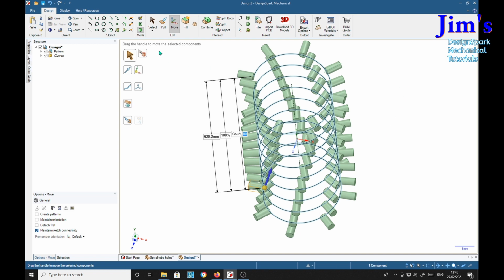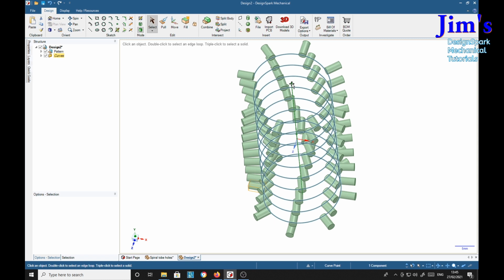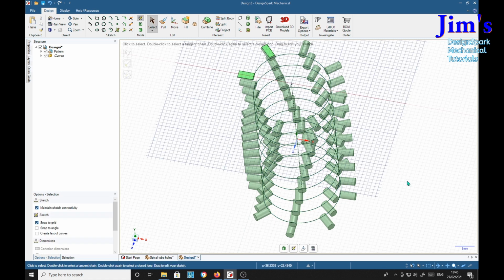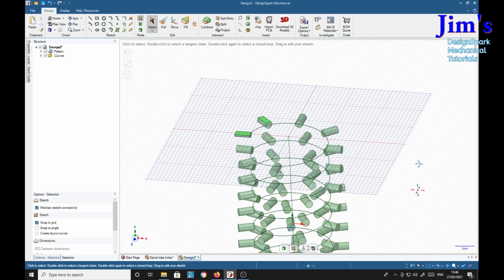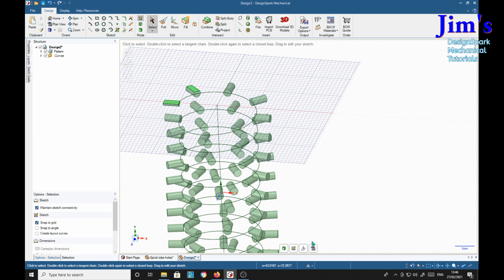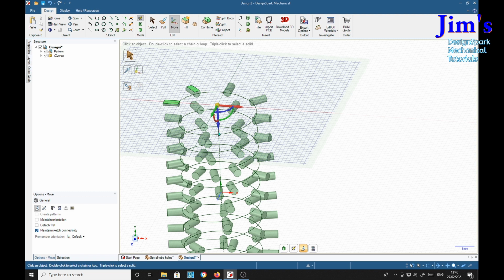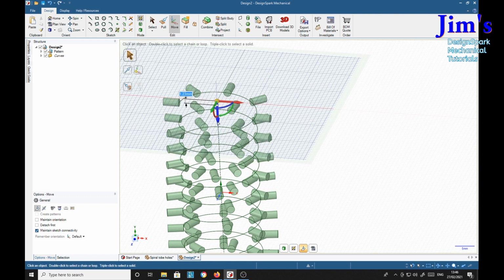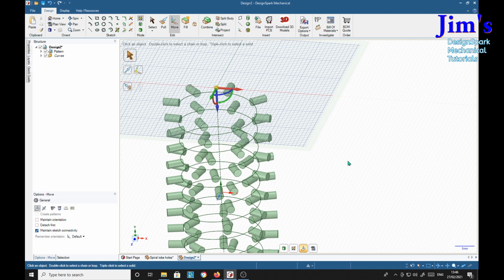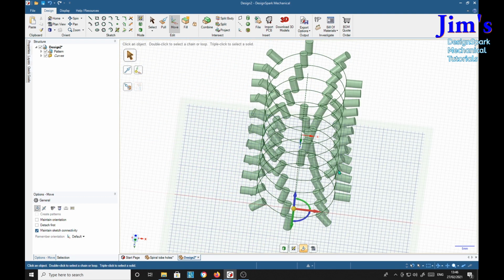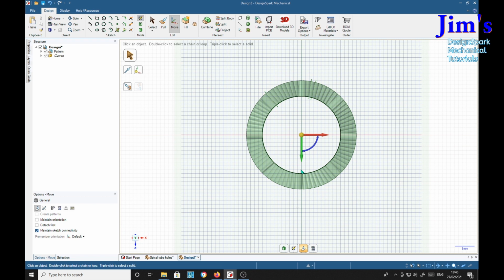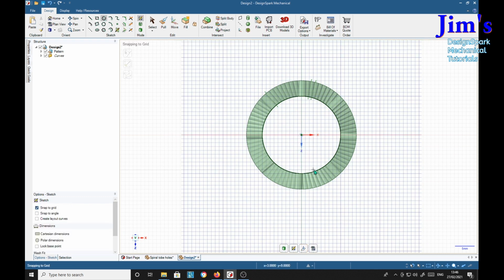So now we select again the end of the center line, and the K key once again to get a plane on it. But I'm going to move it a bit, so down here, this little plane here with an arrow, I select it. I'm just going to move this up 5 millimeters. There we go. So we can see, there we are. Okay, now we're going to put an annulus on top of here.